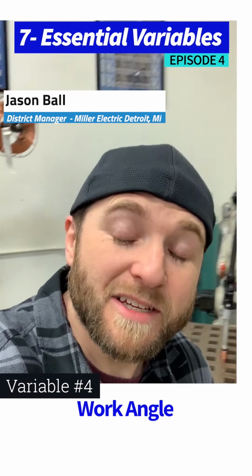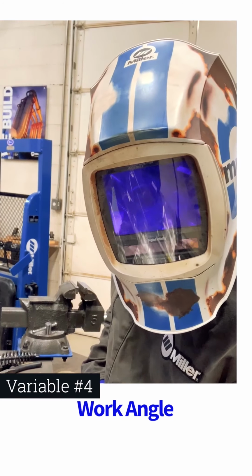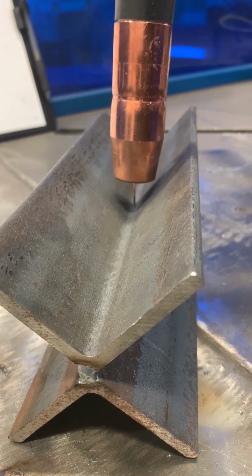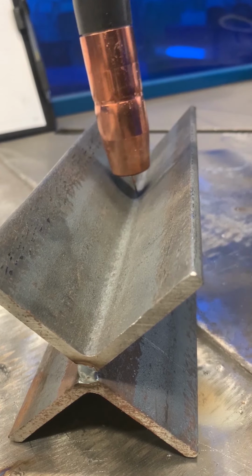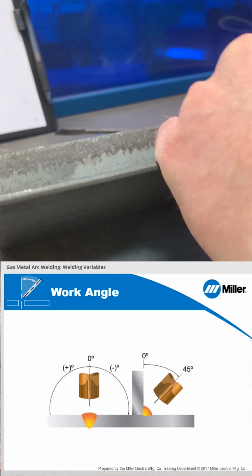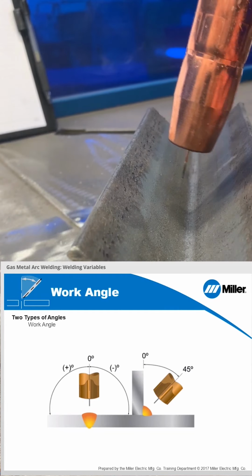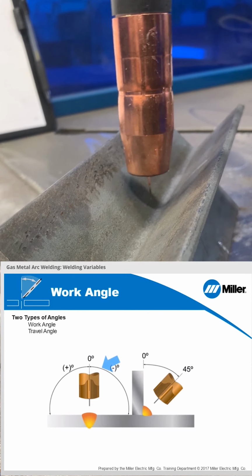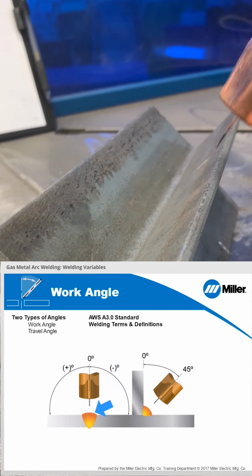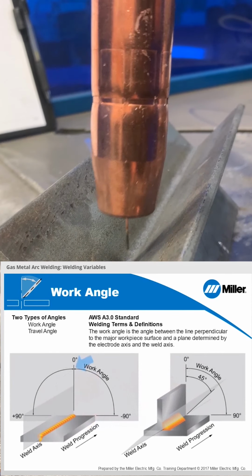So let's continue down the list to number 4, which is going to be work angle. Work angle is the ability for me to control the angle that is perpendicular to the direction of my travel. So if my direction of travel is this way, I've got a work angle that I've got to decide, or I follow a process that dictates, am I doing this at a 0-degree work angle or a 45-degree work angle or a 10-degree work angle, but it's perpendicular to the direction of travel.